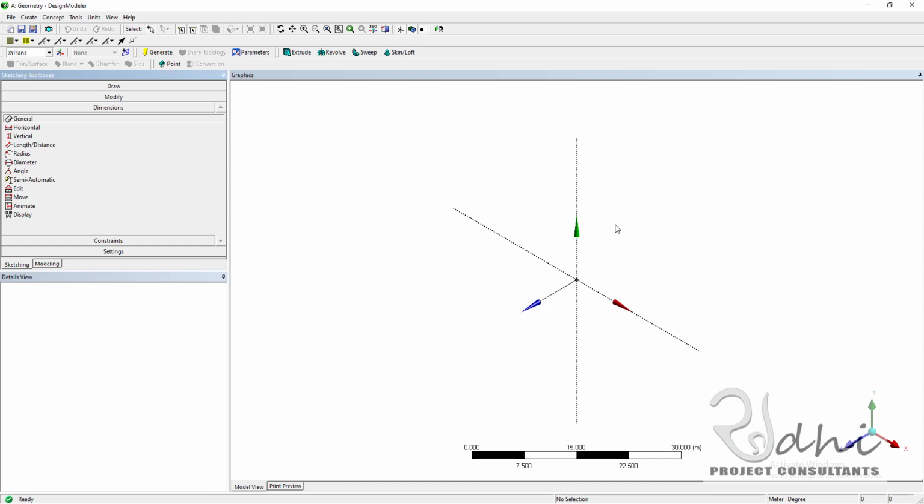If you give any dimension, it means that you are going to edit it, or change the dimension. So if you assign 2 dimensions at the same place, it will create a constrained error, because you cannot assign 2 dimensions to the same entity.